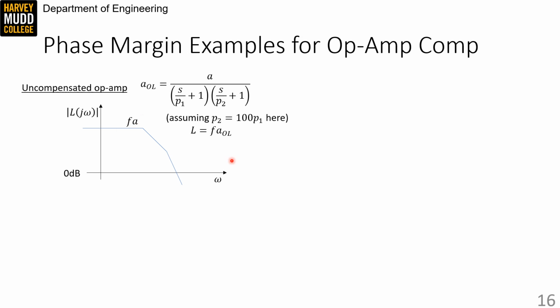Next, we're going to draw a phase plot for this specific magnitude plot. So this one that I've shown, not whatever you have drawn. And we're going to try to assess the phase margin of this op-amp. You have enough information to make a pretty good drawing of the phase, so try to get the phase margin correct. Though I acknowledge that the lack of grid lines and numbers makes that job harder. So pause the video, try to draw the phase plot, and guess the phase margin.